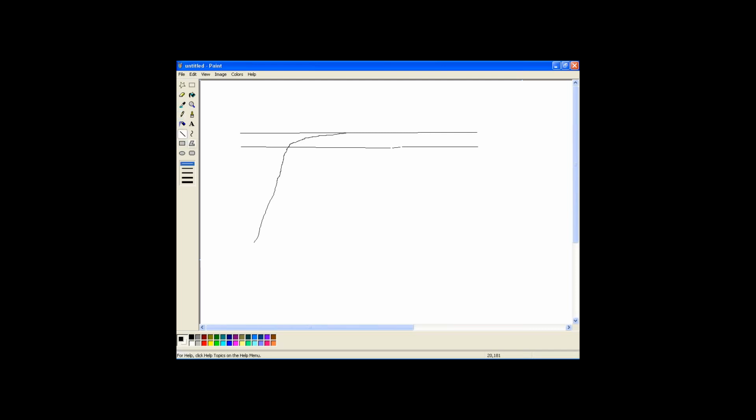So if you make that proportional band bigger, let's say we put in 20 degrees C, then what you're going to get is the same 100% throttle until you hit the proportional band, and then it's going to start backing off at that point. So it will give you probably a smoother ramp into set point, but it's going to take longer because it backs off much earlier.